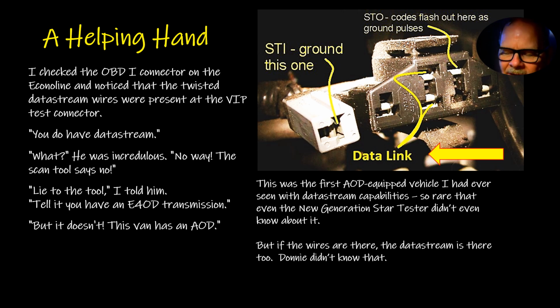Because I used to actually use a meter with a long coat hanger I made that had heat shrink on it except for the very end, and I could go into these wires from a distance and measure the voltage with my meter and all. But it took some doing to do that, and you had to know what all of them normally looked like, and you had to be watching them all the time if it was an intermittent concern and all that. And so he was just sort of bumfuddled because he'd been spoiled by data stream. Now, he spent years like I did working on vehicles that didn't have data stream, but on this particular one, he was flummoxed by that.